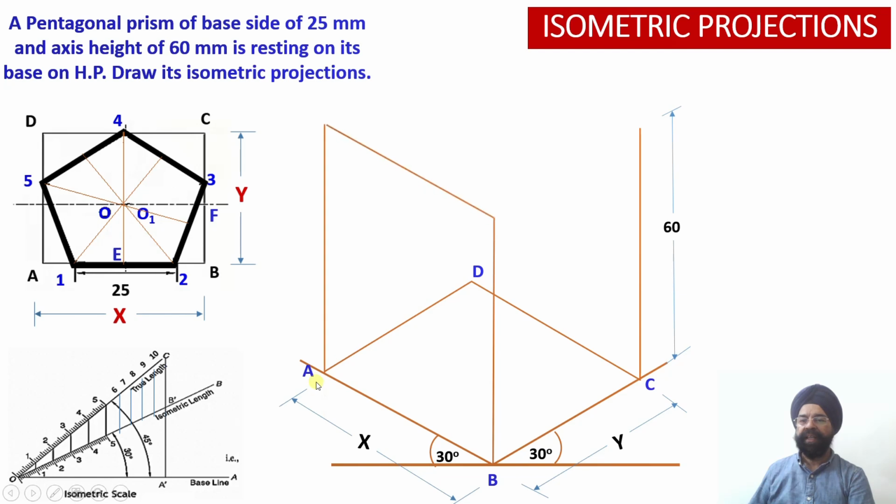Now from the third and the fourth also, right? So all the 4 vertical edges have been drawn, and correspondingly these 2 isometric lines and this one are all parallel to the x-axis. Similarly, these 2 isometric lines as well as this one are parallel to the isometric z-axis, and this one and this one are parallel to the isometric y-axis.